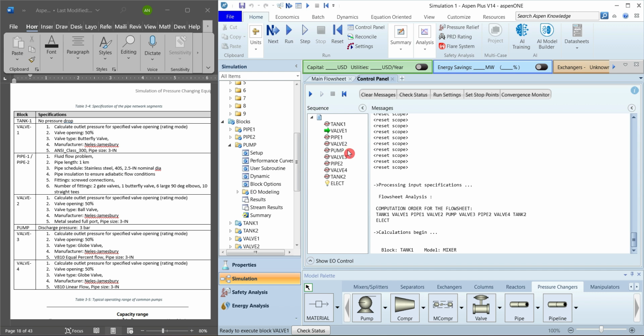At this moment you need to mind the difference between the equation oriented simulator and the sequential modular simulator in Aspen Plus. By default, all the calculations are made using the sequential modular solver. In this case, Aspen Plus solves a stream first, which can be anywhere inside the flow sheet depending upon the sequence, and then gradually simulates unit by unit.